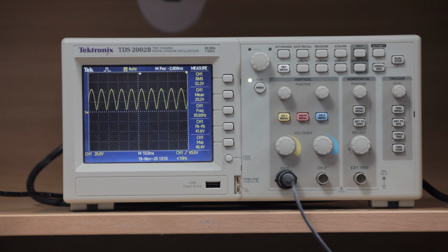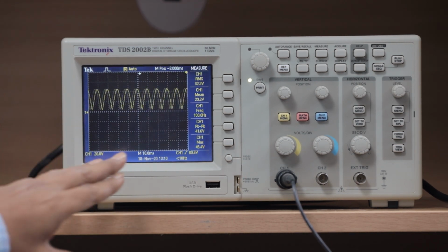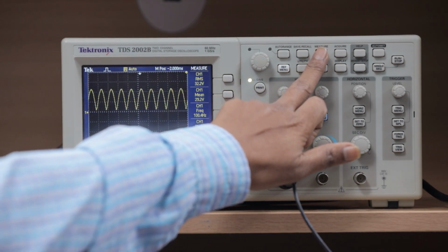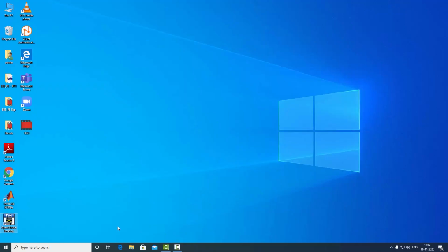Now we got an output across the R and L load. From the waveform you want to measure the mean and RMS voltage by pressing the measurement button. This waveform is at firing angle 0. This waveform you have to capture in the PC.